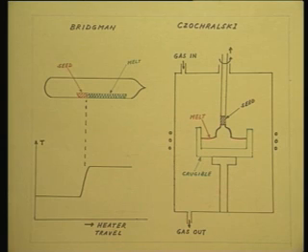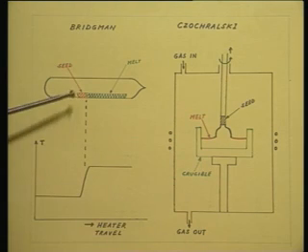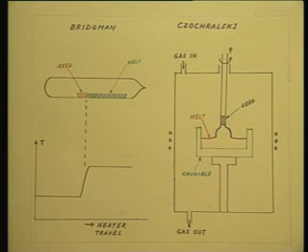Therefore, that end is going to solidify, and since this is in contact with the seed crystal, it will take the orientation of the seed crystal and the solidification will take place as a single event, that is I am going to realize a single crystal. So, as progressively the heater is moved in this direction, from the seed end, the melt is going to get solidified and I am going to realize a single crystal.